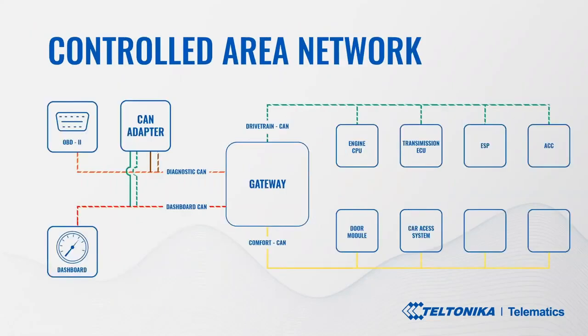To further advance, most motor vehicle CAN networks operate at bus speeds of 250 kilobits or up to 500 kilobits. The latest vehicles use up to 3 separate CAN networks, usually of different speeds, connected together by gateways.